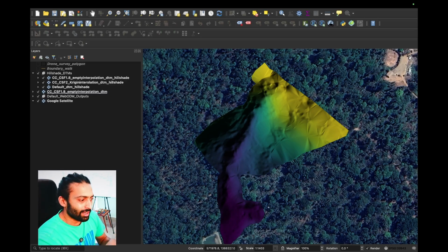I have also gone ahead and tested out what is the difference in the elevations of the cleaned up point cloud versus the default digital terrain model, which is much more raw and aligned with the actual data capture. I noticed that the bottom portions of the valley seem very alike, plus or minus 1 meter, and at the tops it projects much higher elevation values, and by much I mean about 10 to 15 meters at the max in a 900 meter elevation, and the cleaned up point cloud is 15 meters less.